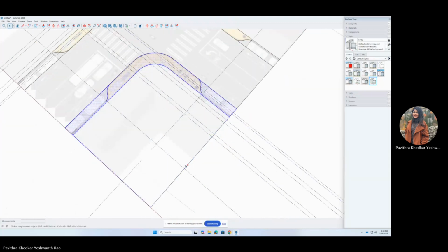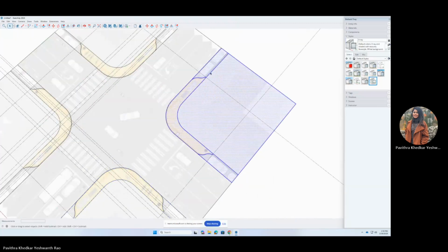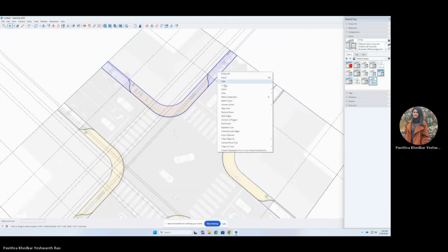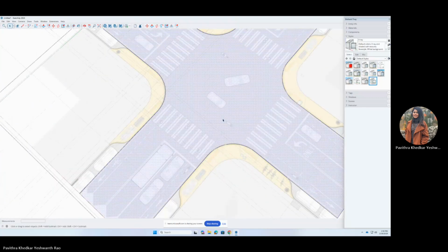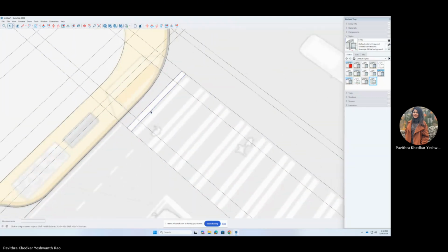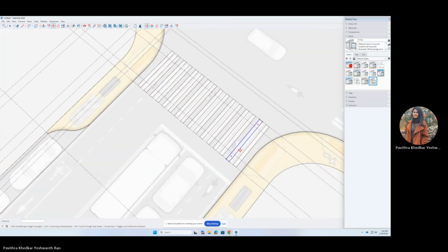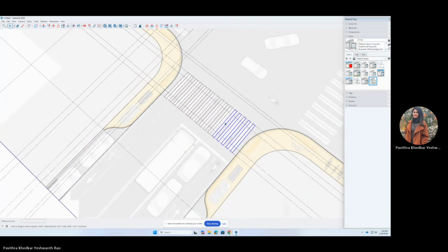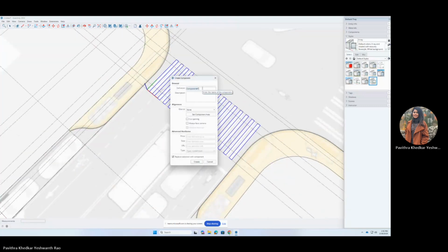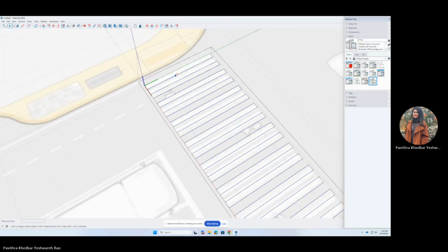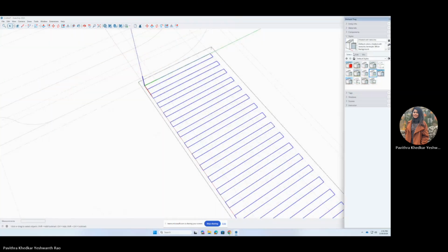Adding road decals and surface detail. Creating pedestrian crossing decals. Design a small rectangular component for a zebra crossing decal. Place it within a group and then create an array to replicate the entire crossing pattern. This ensures any modification to one decal updates in all copies automatically because it's a component.